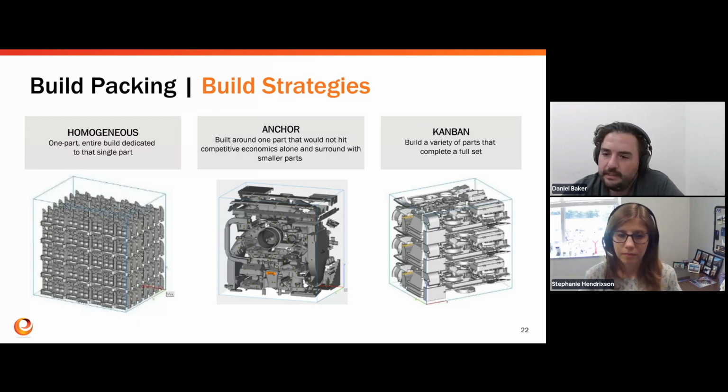But on the design side, with HP, since it's a powder bed process with no supports, you can typically just live with the injection molded design and print it as is, so they're not having to modify it, and you can qualify both together.